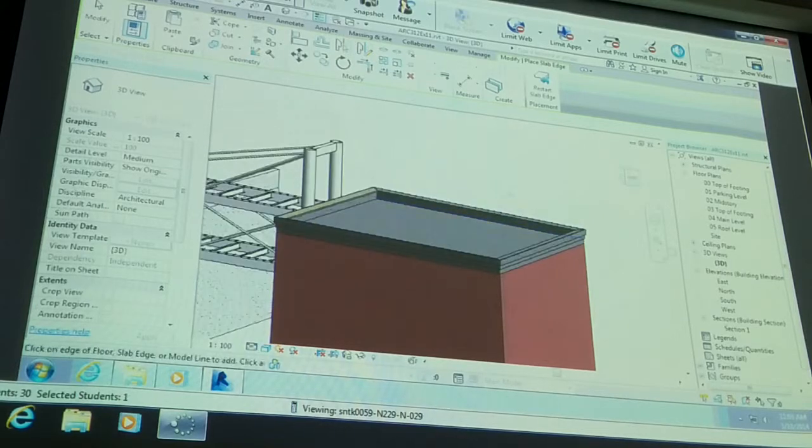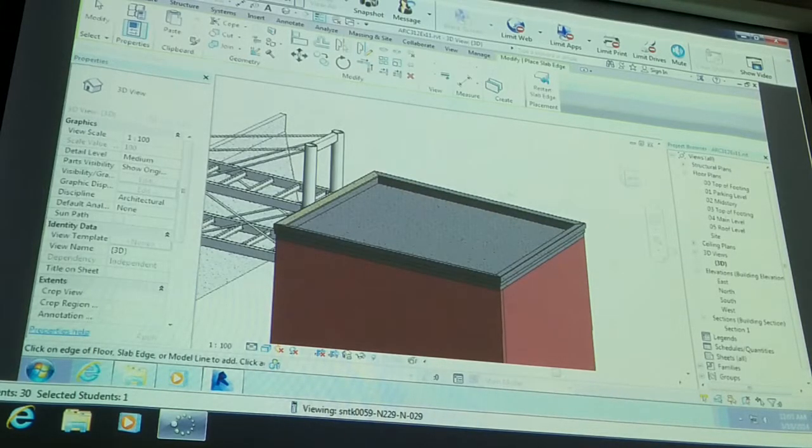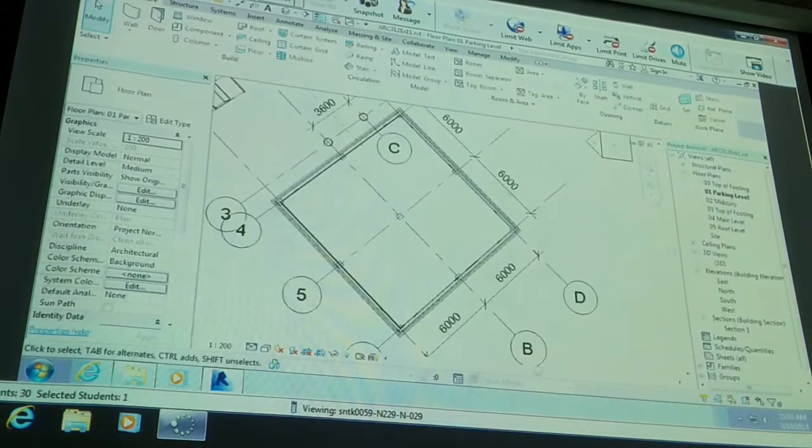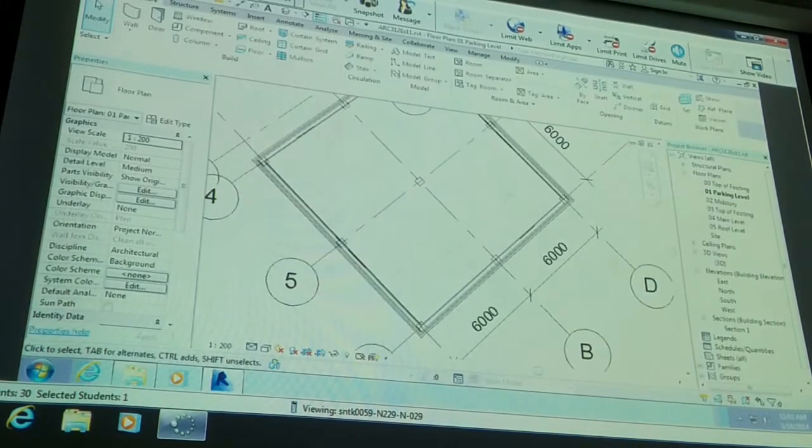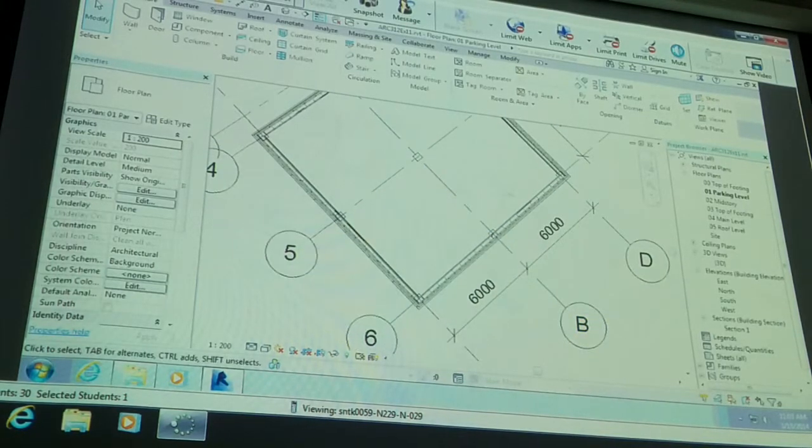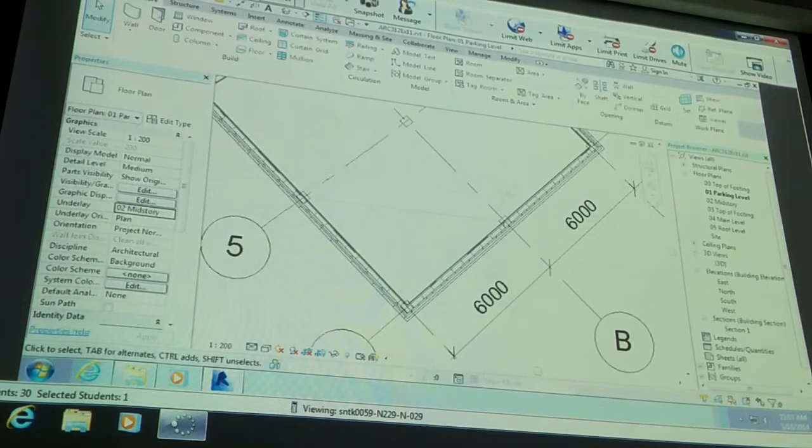Okay, so that looks good. So what we'll do next is maybe while we're here, let's add our stair. So let's go back to the O1 level and we'll draw our stair here. So going to the O1 level, it would be helpful to be able to see the floor above. So let's put the O2 level in as an underlay. And it would also be helpful to have a little bit of layout geometry here at this level.